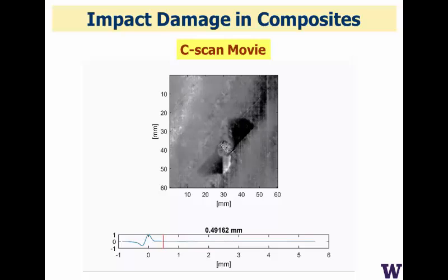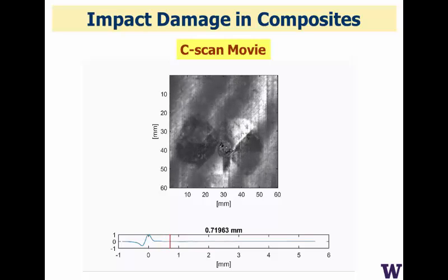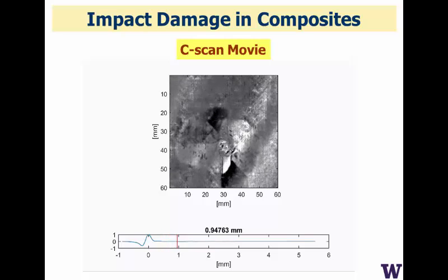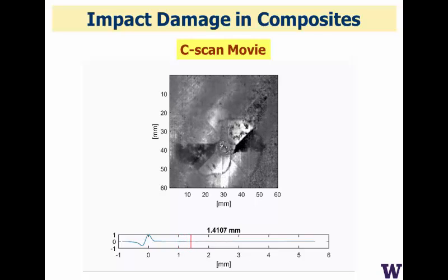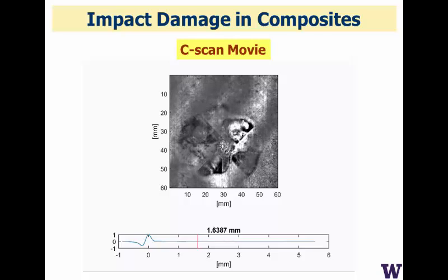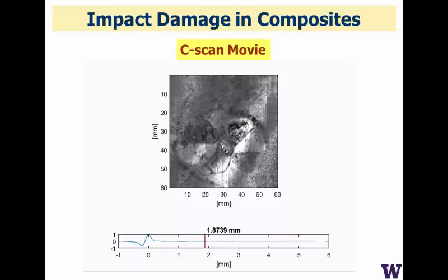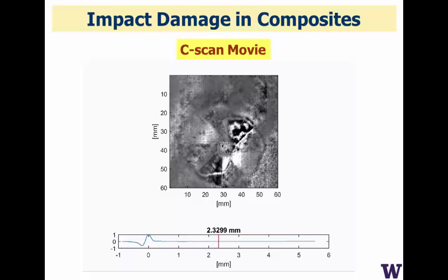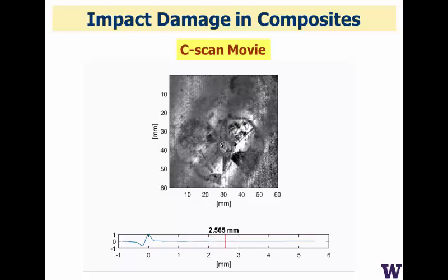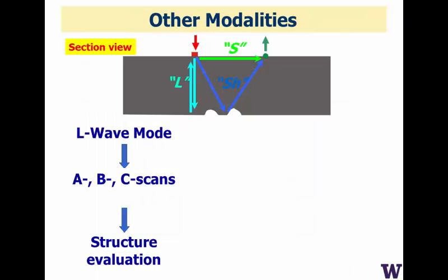And so you can follow that structure. So that's where the damage is, and you can follow it as you go with depth as it rotates from layer to layer in there. And so you can quantify the damage in those layers. When we showed this to our aerospace colleagues, they first thought these were X-ray images, but no, these are non-contact high-speed ultrasound pictures of this.